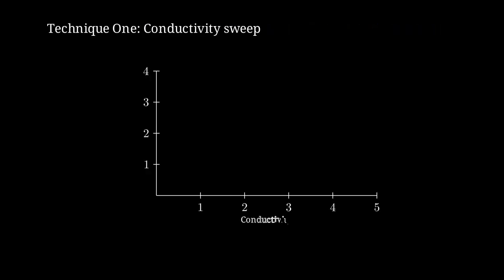Plot velocity versus conductivity. ACEO gives a flat line. Electrothermal gives a line with positive slope. The measured data is the sum. By fitting, you can extract both components.